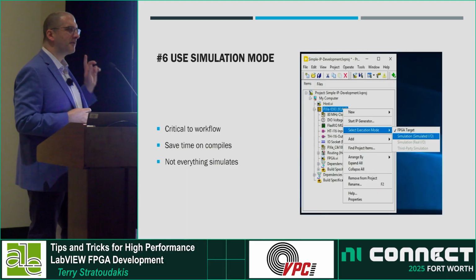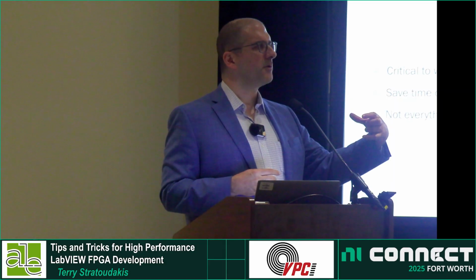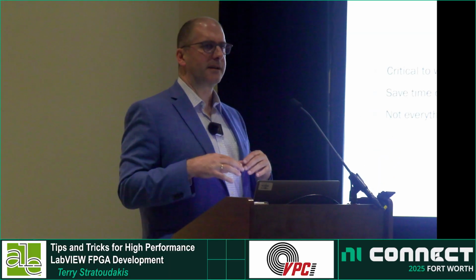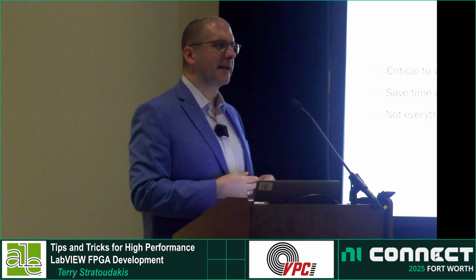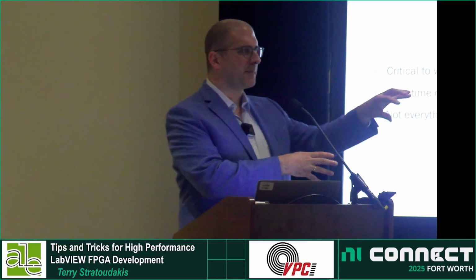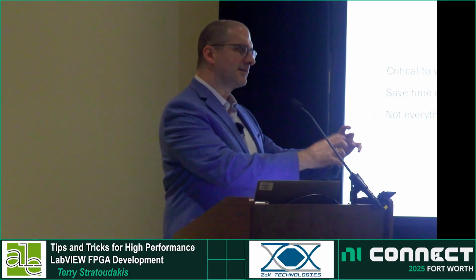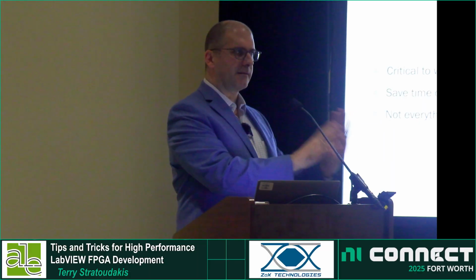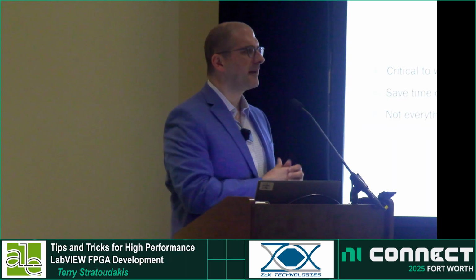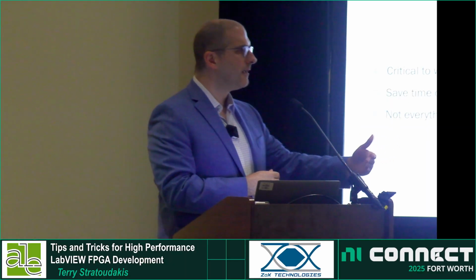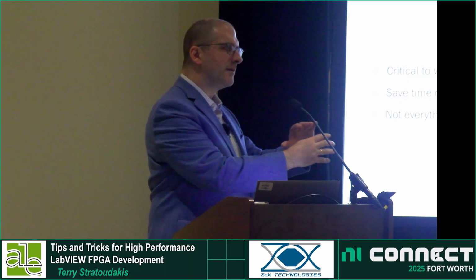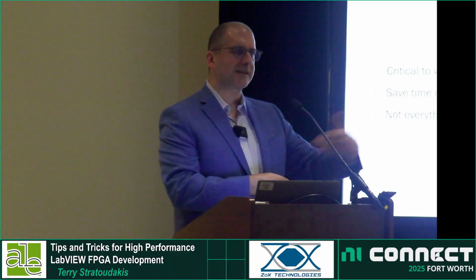Now, not everything simulates. For example, those IO nodes that I showed you earlier don't simulate. Peer-to-peer doesn't simulate. There are certain pieces that do not simulate. And what's the answer to that? The answer is to modularize. So if I have peer-to-peer and I'm doing some functions, I'll make an example to fully understand how that part that won't simulate works. I make a separate example for that which proves out how I'm going to use it. And then for my blocks that can simulate, I make a standalone test bench and study that. I could put my own test signals in there.